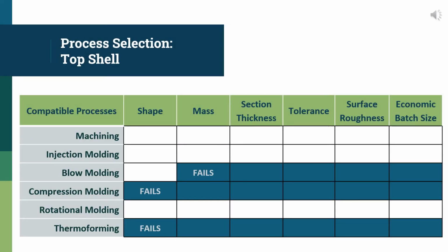Both the upper and lower housings were analyzed for process selection. Based on market size estimations, we anticipate a combined production run of approximately 1 million units. ABS was chosen for its high strength-to-weight ratio, aesthetics, and impact strength. Using snap fits and redesign dictates use of a non-metal, and based on this, candidate processes are shown below.